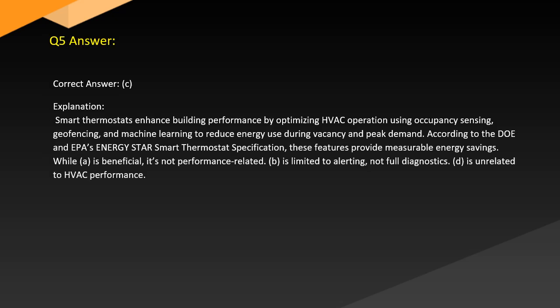Answer. Correct answer: C. Explanation. Smart thermostats enhance building performance by optimizing HVAC operation using occupancy sensing, geofencing, and machine learning to reduce energy use during vacancy and peak demand. According to DOE and EPA's Energy Star Smart Thermostat specification, these features provide measurable energy savings.